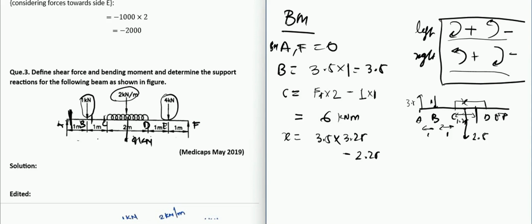And also we have a force of 2.5 acting at, this will not be here. So the force will be acting at the midpoint of this. The entire force will be acting at the midpoint, which is 1.25 by 2, so it will give 0.625. So yes, you need to calculate at that point.